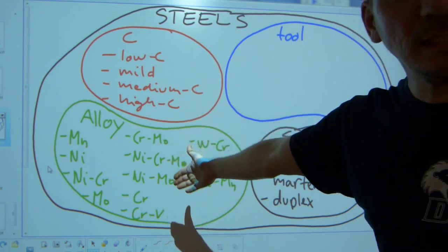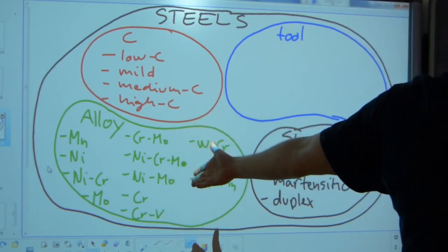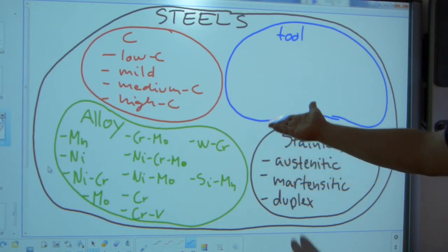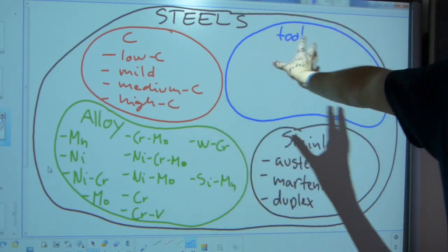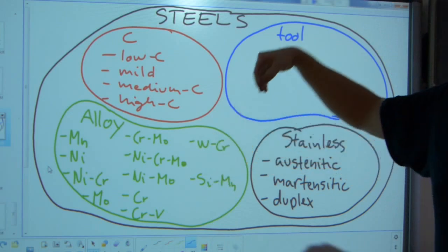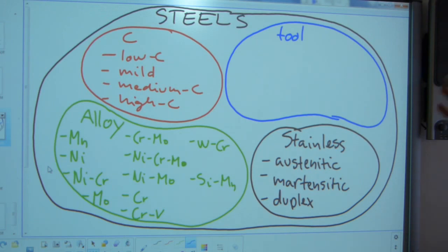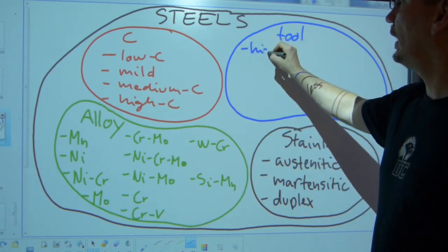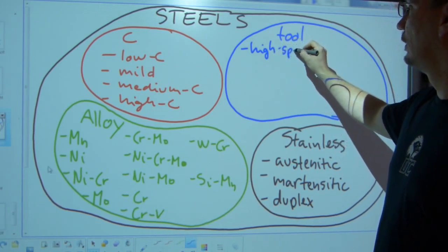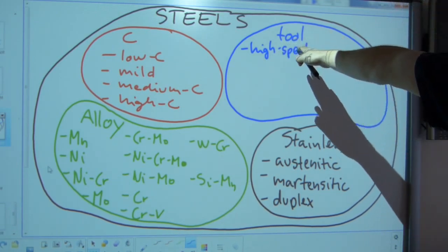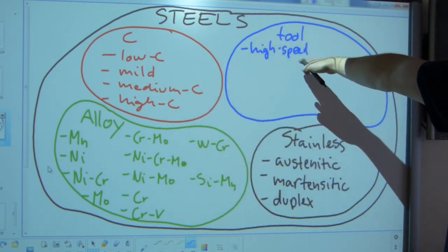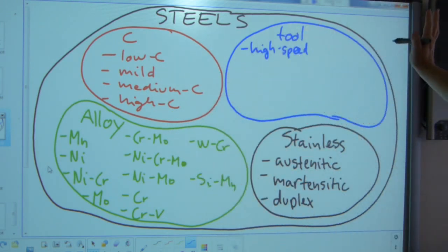So if you have wrenches, you saw the chrome vanadium wrench on the table, don't get confused with what's being made of the steel and how it's actually named, okay? So that's tool steels, that's the name of the group. Inside the group there are 4 major groups, and 2 of them will have little subgroups. So we have high speed tools. Don't confuse it with high carbon steel. High speed steel, high carbon steel, completely different animals, okay?